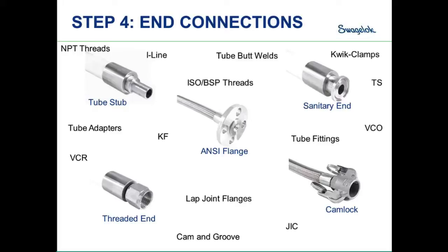And what I mean by that is, if we were trying to mate up with a certain standard and the end connection wasn't integral to the hose, we'd have to use an adapter. Now, anytime you use an adapter, you've now put a potential leak joint into your system, depending on what type of fitting you're using. But I think most importantly, when you think about it from a hose standpoint, hoses are typically used because of the need of flexibility. So anytime we add an adapter, we reduce the amount of flexible hose being used. So having that integral as one piece could bring a lot of value to your application and, again, prolong the life of the assembly.